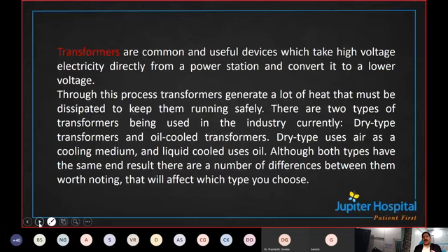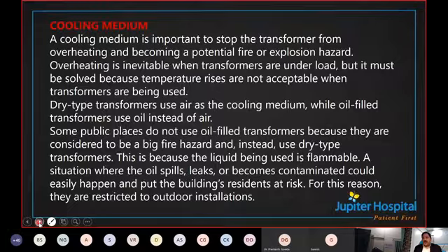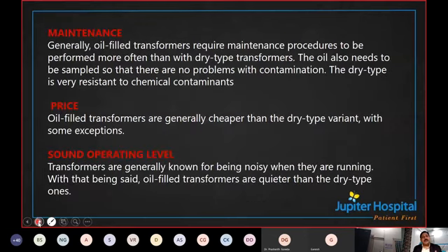And that is why most times, if it is possible, and from the safety point of view, most places are going with a dry type transformer. But it is not so that people are not going with oil. Those who have a big plot do the oil one also, because of the saving in the initial stage. But if you ask me, the maintenance of the dry type is much easier than oil, because I'm using both at different locations, and our experience is that dry type is much easier to maintain.